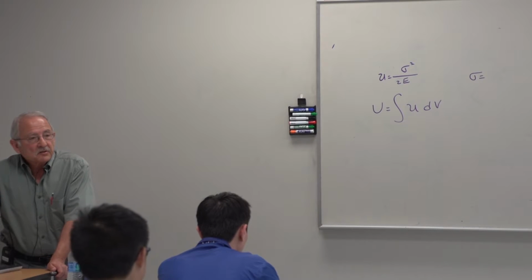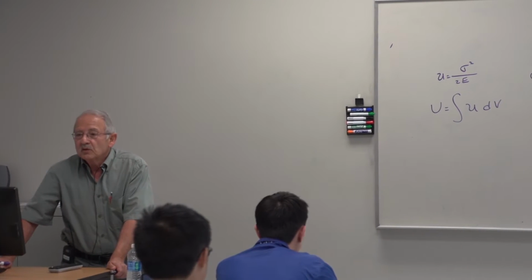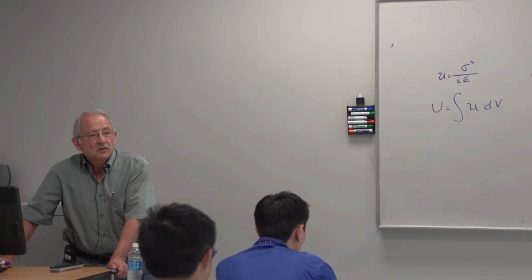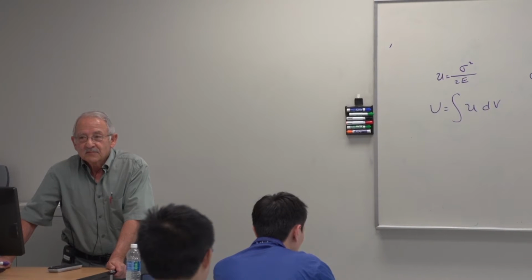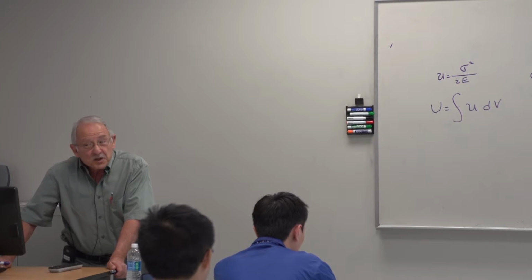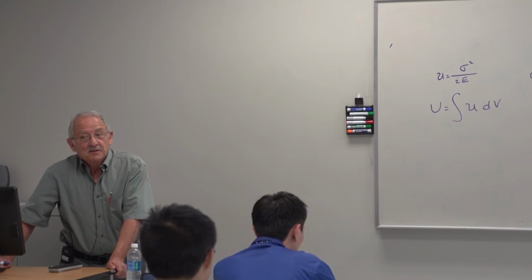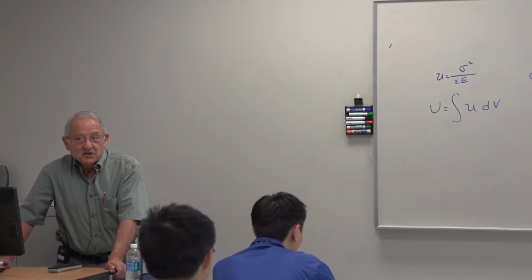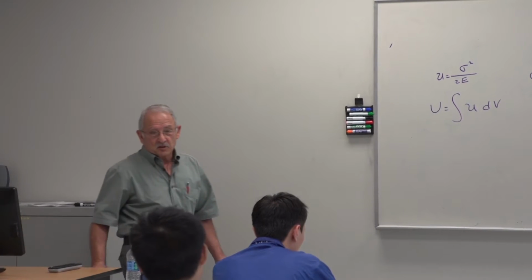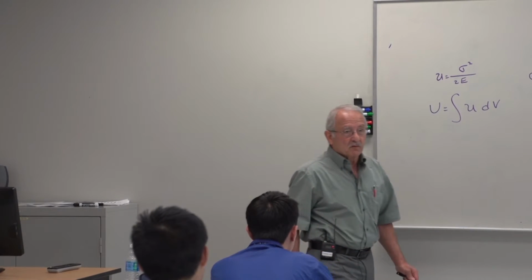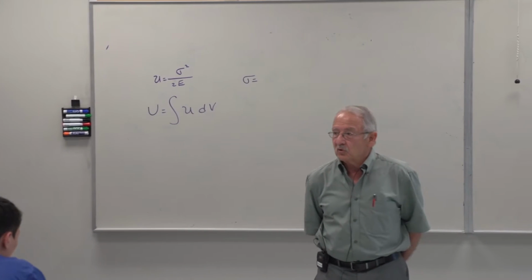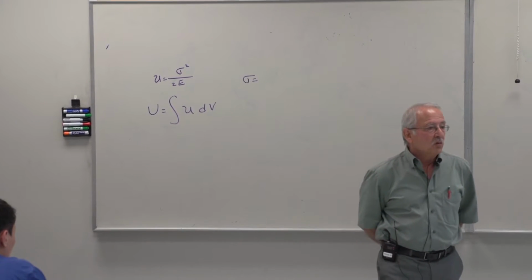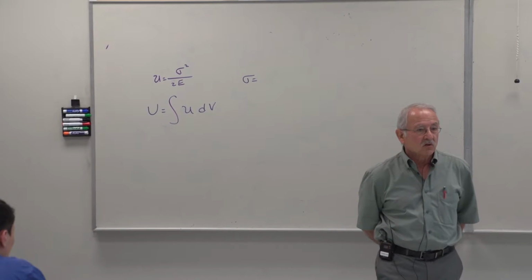And in bending, the stress is equal to, remember the equation? Only if you're looking for the maximum stress. But in general, that's not the equation. It's My over I, right? Where y is the distance from the neutral axis to whatever element you are looking at.